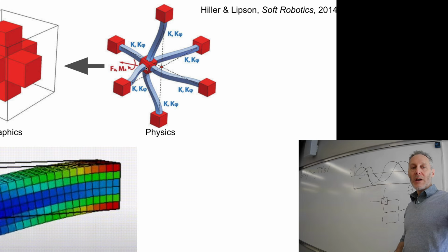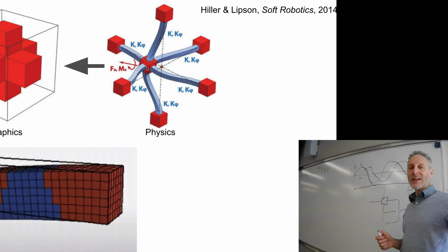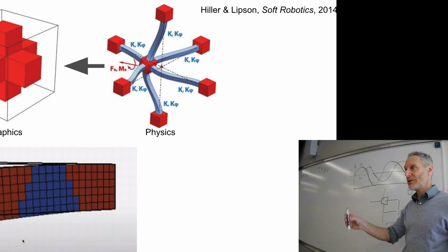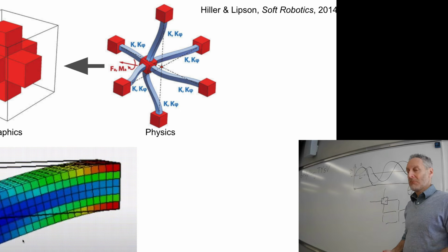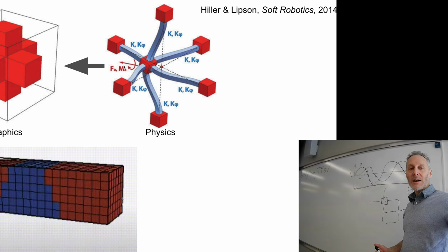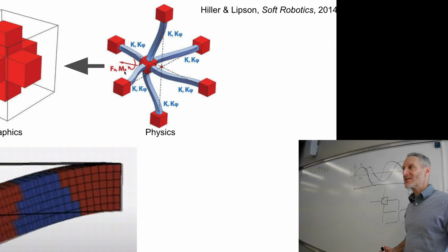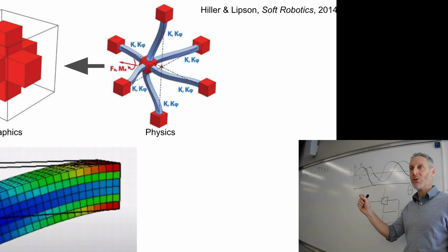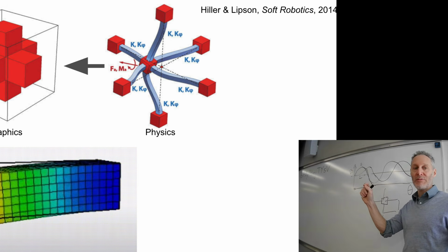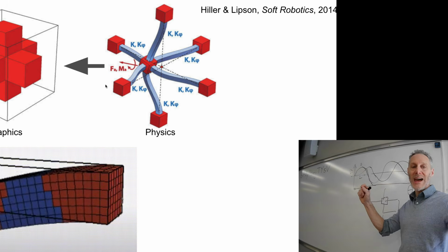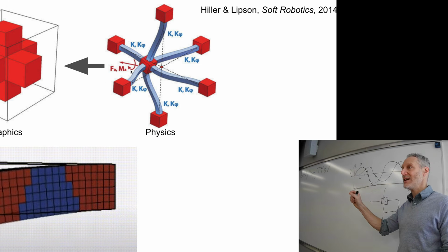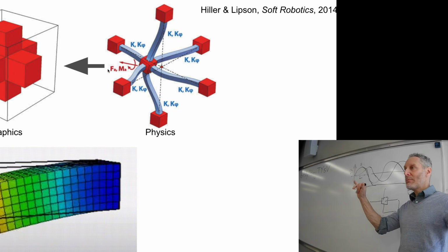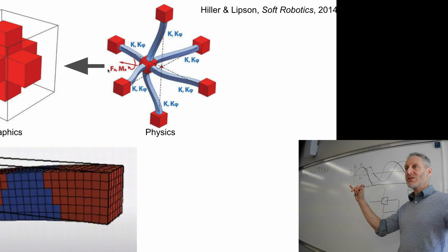Okay, so VoxCAD knows all the forces that are acting on this cube, including, for example, the downward force of gravity, whatever else is going on. It sums up all the forces, it knows the masses, and it uses F equals ma. It rearranges that equation so that it uses F and M to compute A, acceleration. F, remember, is a vector of 6 numbers.